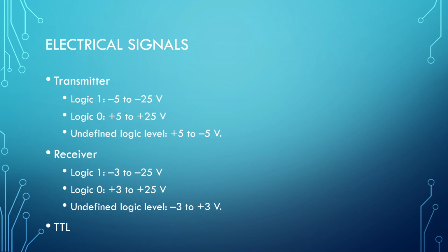That'd be your current. But anyway, you can figure out how much power loss we have, because you can say, well, 1,000 feet of this cable has 2 ohms of resistance, and if we're going to be running at 5 volts, we can figure out how much current we're going to be using. Once we know the current, we can figure out what our voltage loss is.